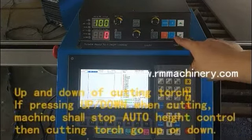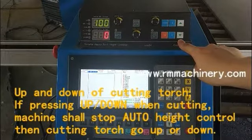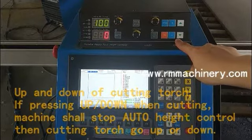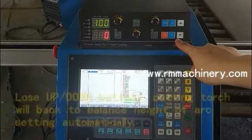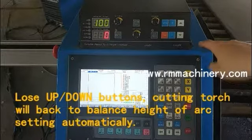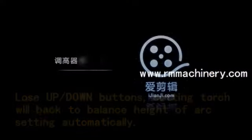Up and down of cutting torch. If pressing up/down when cutting, the machine shall stop auto height control, then the cutting torch goes up or down. Release the up/down buttons, and the cutting torch will go back to the balance height of the arc setting automatically.